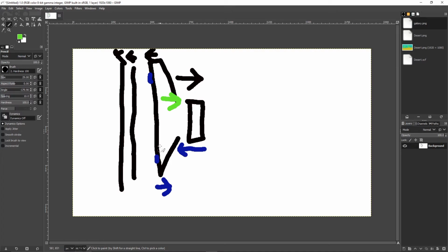This allows the pressure plate to, I don't want to say warp, but go back to its original position and push the clutch again. So when you're not in the vehicle and you've got no feet on the clutch, it's pushing all the time. It's always trying to be engaged, right? When you push the pedal down, that is when it actually separates, which is why you can leave your vehicle parked on a hill in first gear and walk away from it, and there's this mechanical connection between the engine and transmission, and it won't roll.